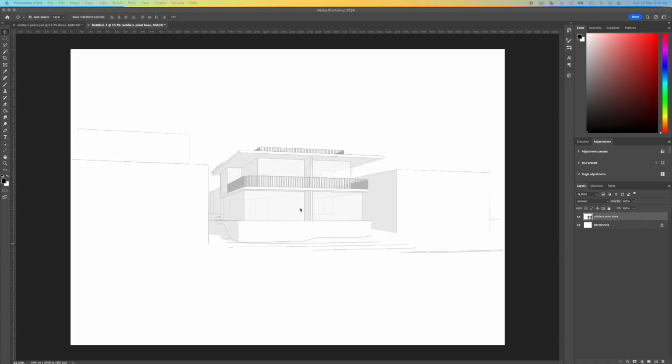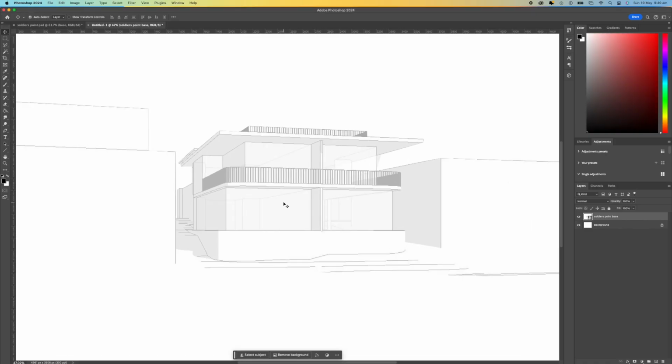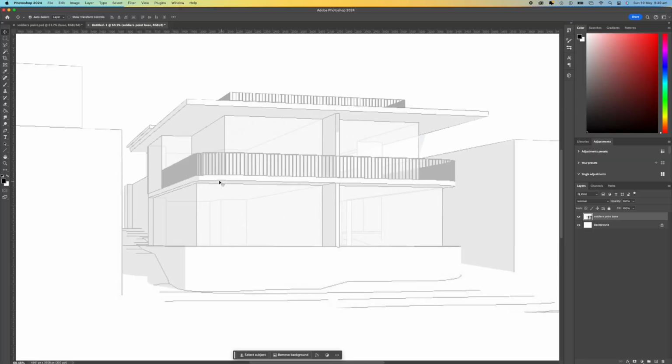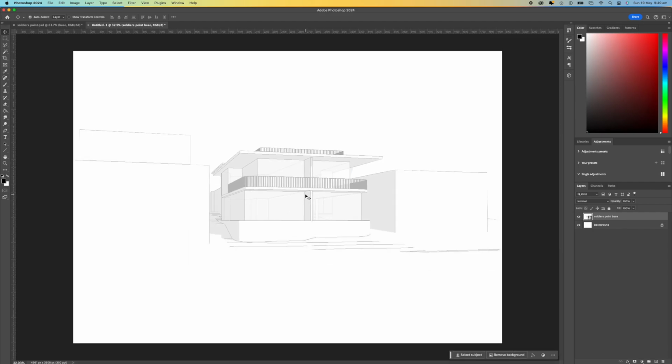If we have thick lines like this, it does make it much harder, so when you're turning the drawing off later, it won't end up with lots of heavy white gaps between all of the textures. And then you'll have to go and edit all of the textures all over again. So you really want from the start to make sure that you're doing it correctly and adding your perspectives in with the thinnest line weights possible. You'll see in my demonstration that this does get a little bit messy, so yeah, nice clean line weights are really good if you can use CAD software to draft up your perspective.